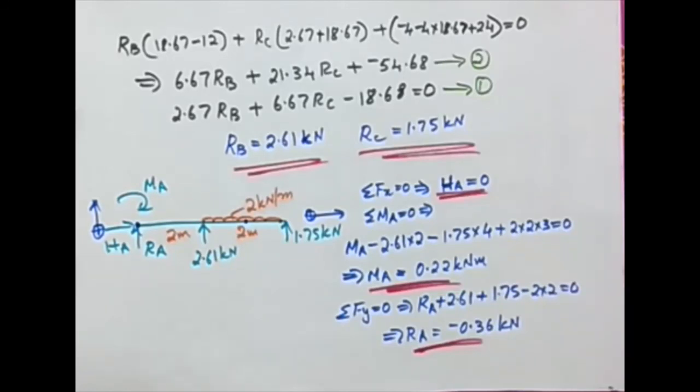So this is a basic method which is very practical and very easy when we are dealing with structures having single degree of indeterminacy or maximum 2. You have seen already when it is 2 how lengthy the calculations are going to be. So this is how we do the analysis for an indeterminate beam having degree of static indeterminacy equal to 2 using the strain energy method. Thank you.